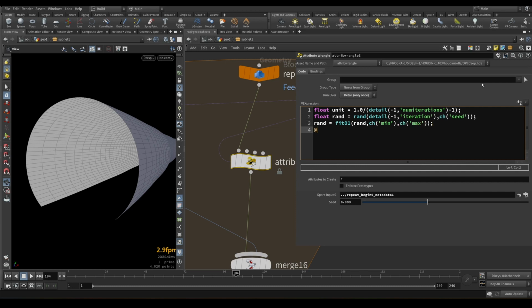And then we will generate an attribute called previous, and it would be plus equals itself plus unit plus random. That way we reference the value from the previous iteration and we have set it to the new iteration. Because we didn't initialize this and because this is a float attribute by default, it would be resolved the first time as a 0.